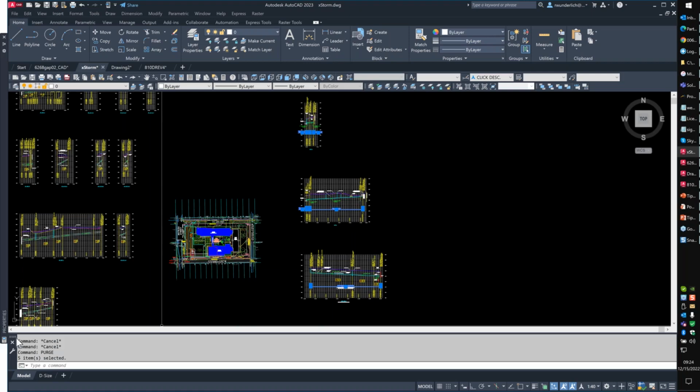Abby, you're talking about point cloud. How can AutoCAD bring a 3D point cloud and change it to 2D? You can't. A 3D point cloud is just that, a 3D point cloud. You can't really change it to 2D because you can't bring it directly in here. You're actually attaching that point cloud as an external reference. So what you may need to do in that case is trace over it, or do something slightly different so that we get some different results. But that's how we use that purge.